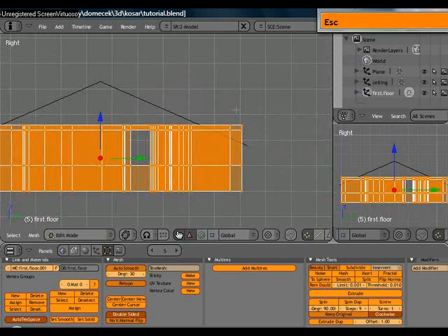But I don't like to do that because it's very difficult to make a cut that is exactly following this roof here, and especially if you do multiple cuts through multiple walls, then each cut will be slightly different, and it will also modify the geometry and the faces, and it'll create triangular faces, and it'll make it difficult later on to create loops and insert textures. So I'll do something else, but for that I need to prepare.